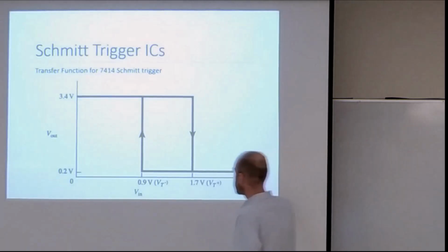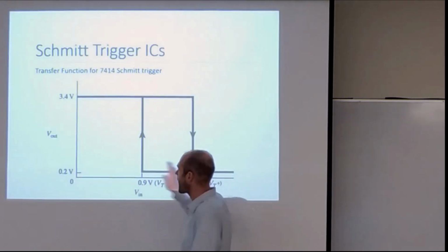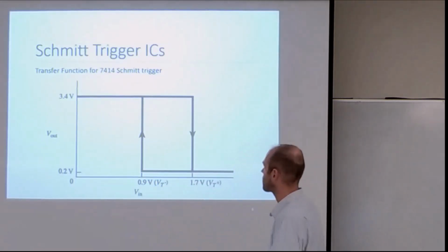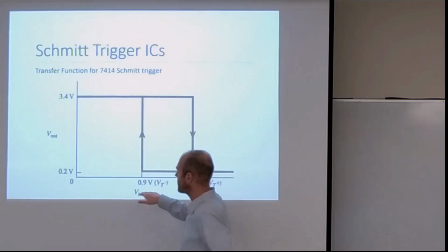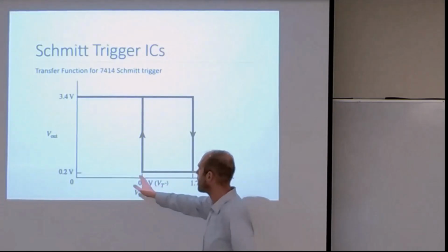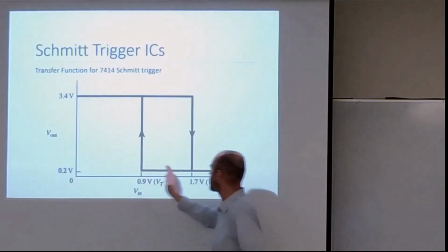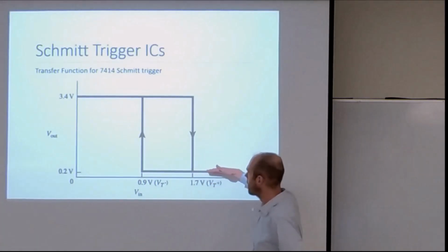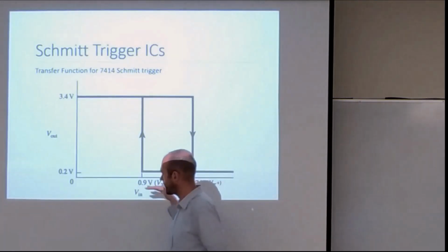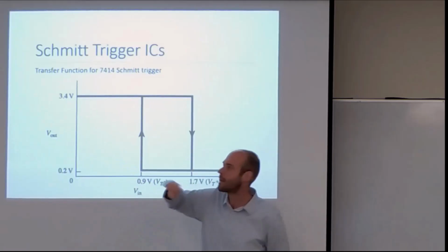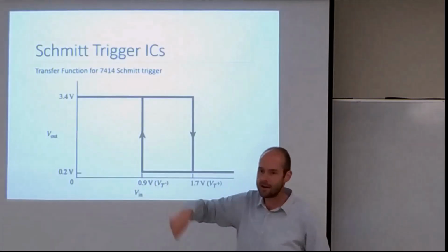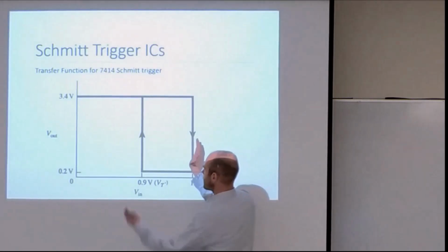Hysteresis means looking forward and back on the transfer function, a term you will use in future classes. You're looking at the input on the x-axis versus the output on the y-axis. For an inverter, if your input is low, your output is high, and if your input is high, the output is low. For a standard inverter, the forward and back lines would be the same.